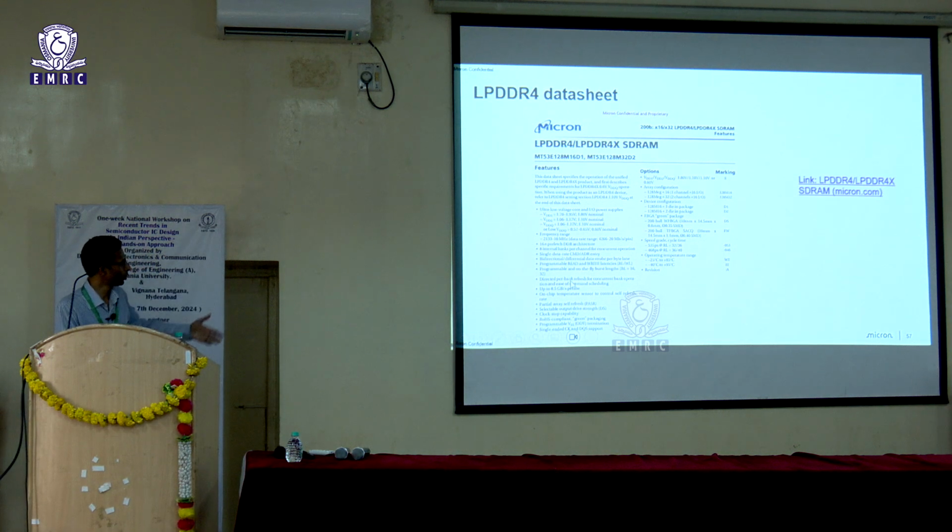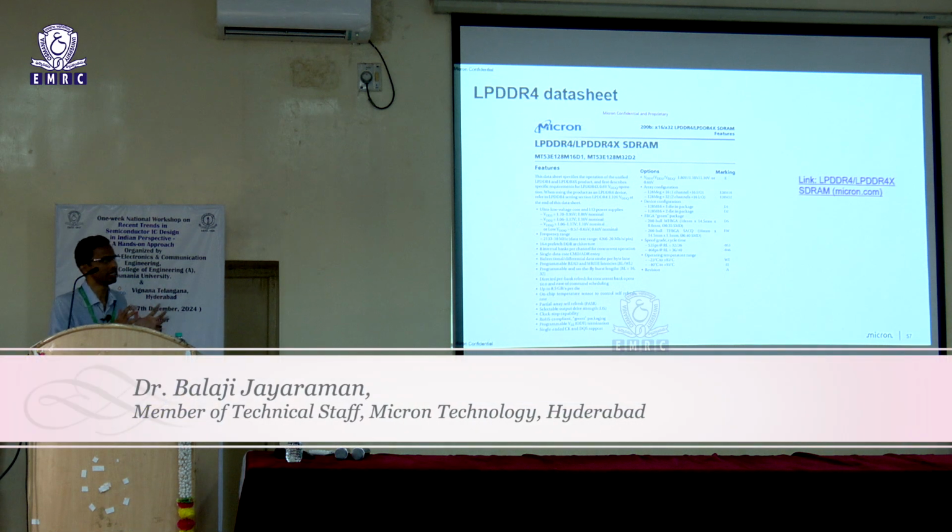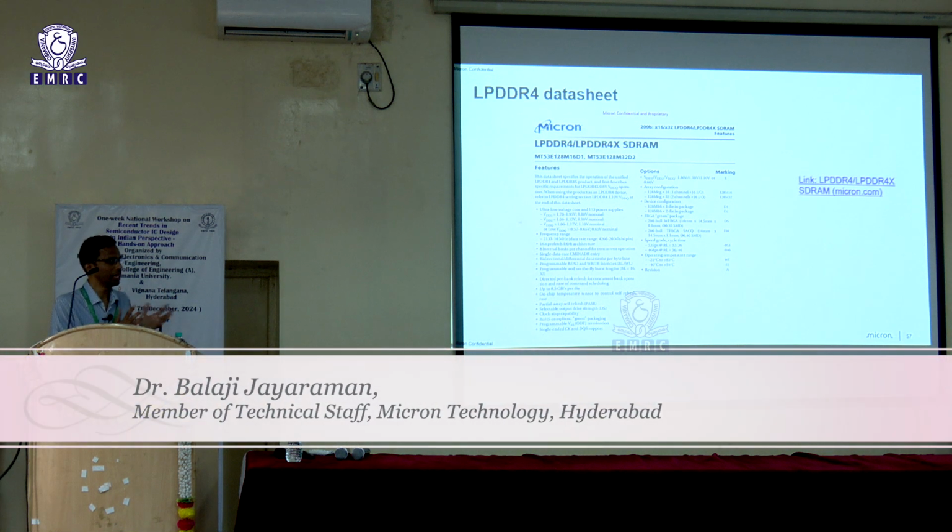We have a 16-bit architecture here, and there are 8 banks here and single data rate command. If you look at this now, you would at least have got an overview. It may not look so overwhelming as it would have if you were looking at it for the first time. So, we have covered most of the topics here. It gives you a gist of what goes into building a memory system.